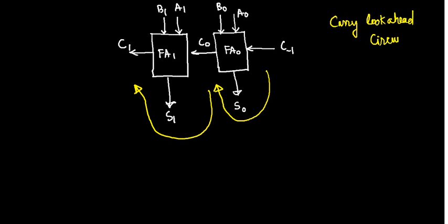So that is what we are going to see here now. For that purpose, a full adder is there. I am simply representing the full adder expression with an index I. Si indicates the index of the bit number, right? So Si, what was the expression, you tell me? A XOR B, right? Ai Bi. I have represented that by P, so that is Pi, XOR with C of I minus 1.